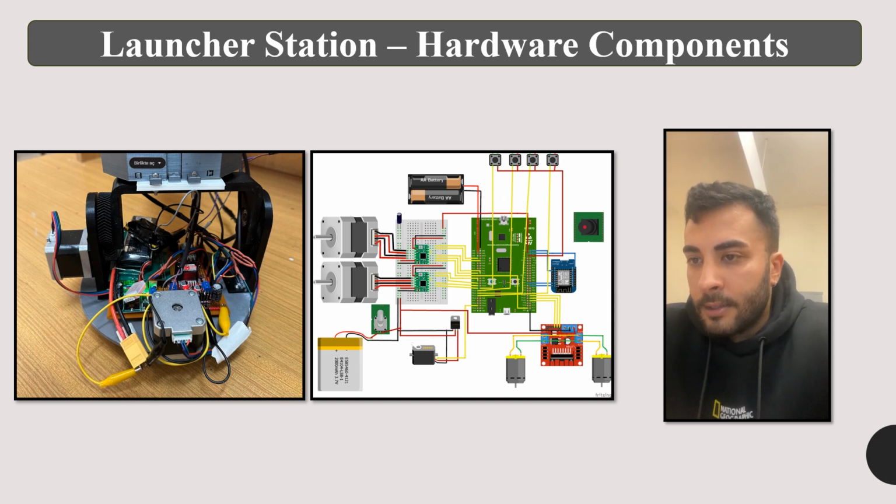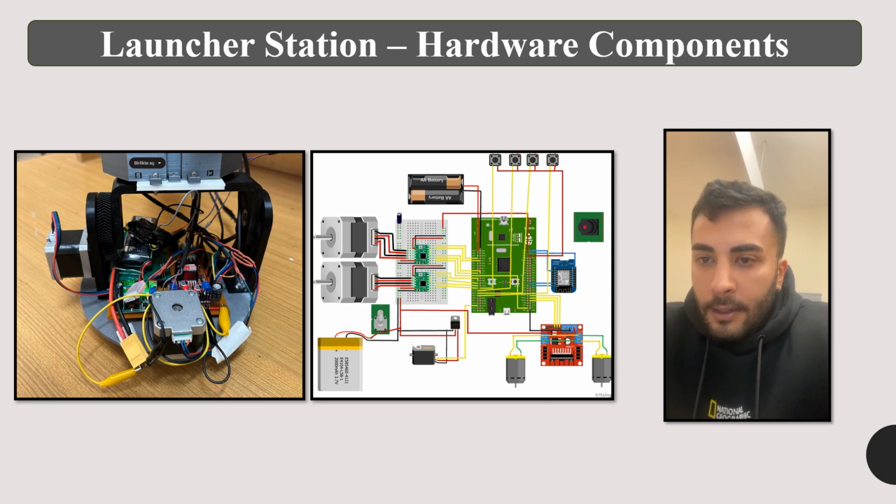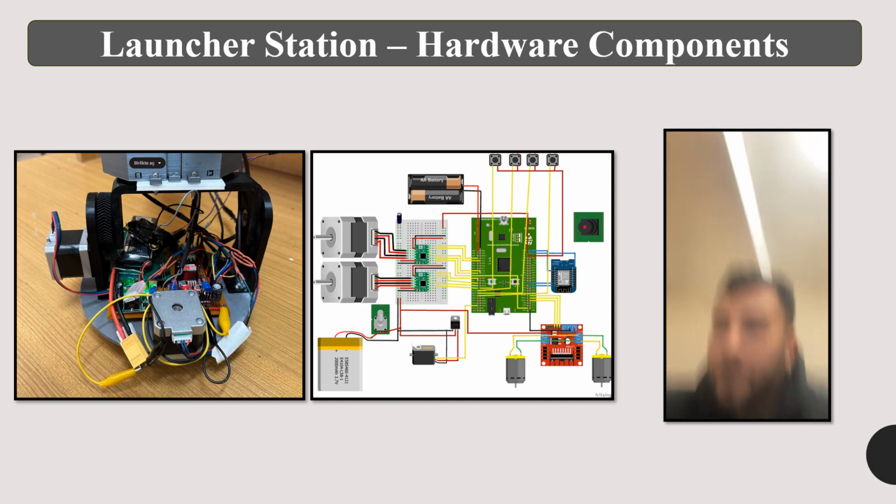STM32F407 was used as the microcontroller to control the whole system. A 3S 11.1 V LiPo battery was used to power the whole system. A 100 microfarad capacitor was used to reduce the noise of the battery.